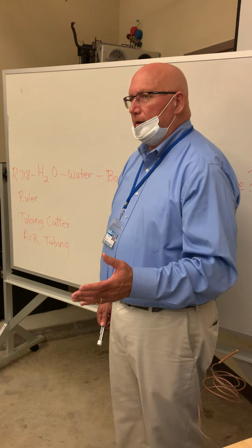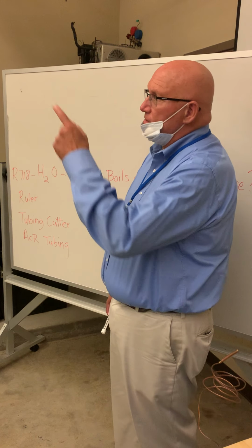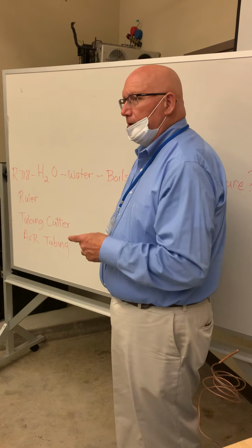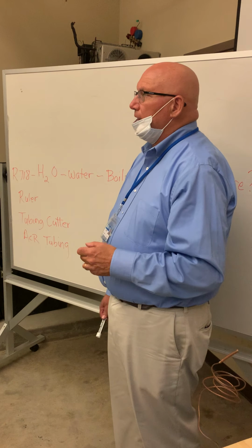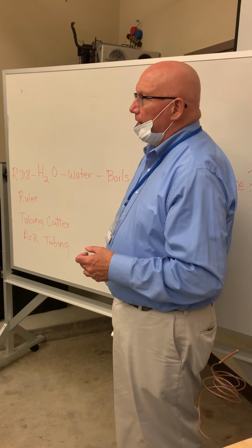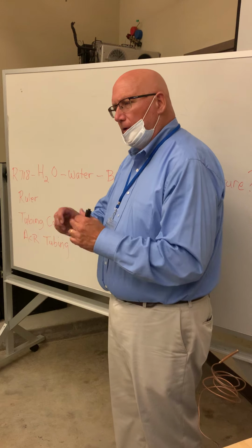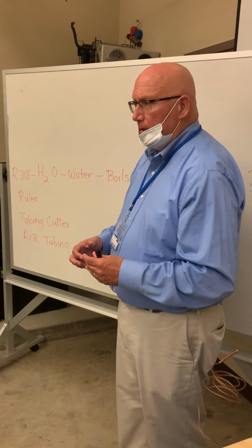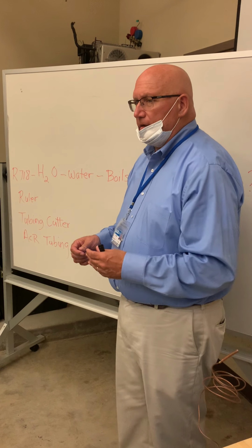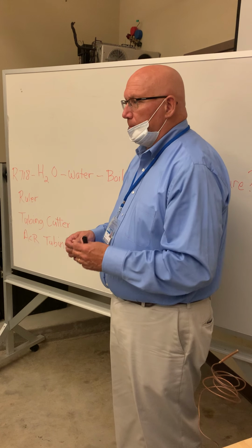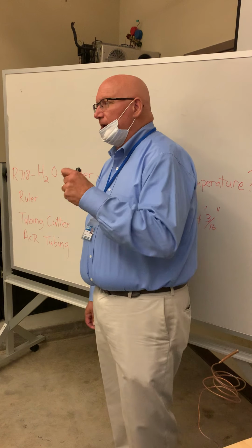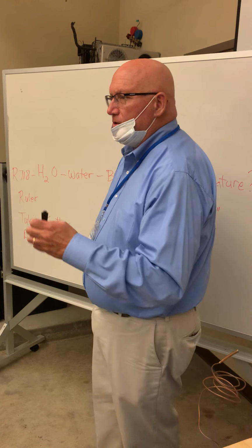But let's just think about that. In order to work on this unit, the students have to go up either that ladder or that ladder. And if you're all the way up there and you're trying to focus in and get the wiring correct, which you will have to do, and you did not realize that the power was off, and you get a shock, even a slight shock, what's your reaction?